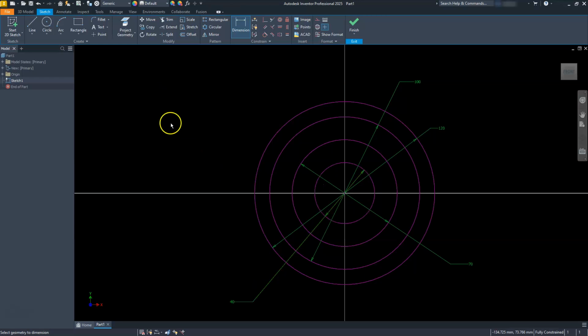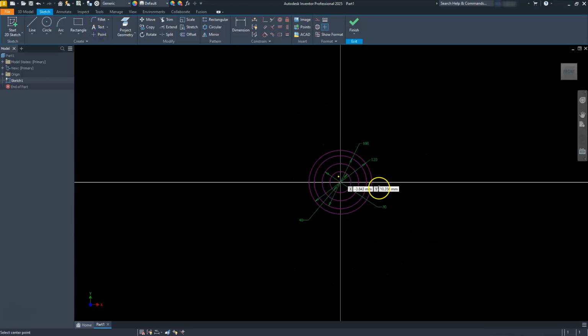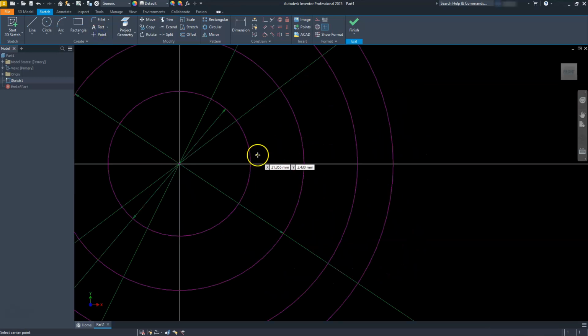All right, let's go ahead and create those points. We're going to use the points, which are located here. Just going to slide this over so we can work here. So you can see my 3 points that I have created. Let's add the constraint to them. I'm going to go with a coincidence. I'll select the point, select the line, select the point, select the line, point, and line. All right, let's escape out of that.